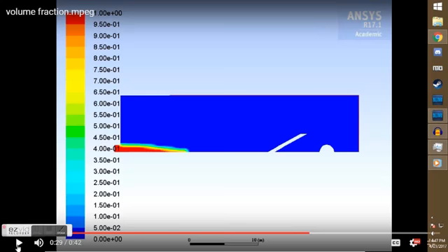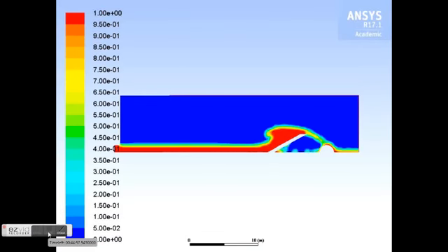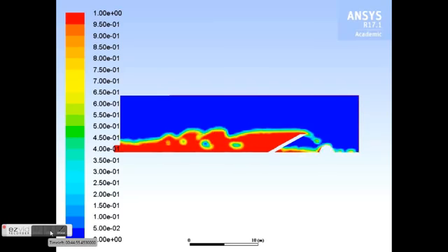The following video shows the desired water behavior in the Fluent solution. Note the jump forms shortly after hitting the ramp, although it quickly submerges below the backflow. Also note that a reverse jump is formed on the right side, where the geometry and drop induces critical flow again.